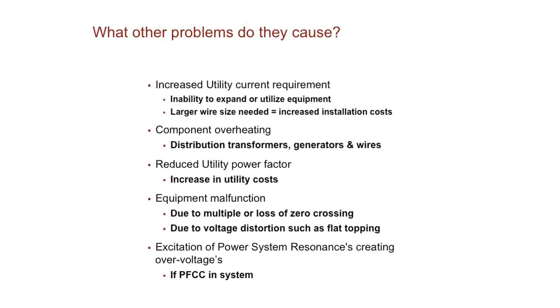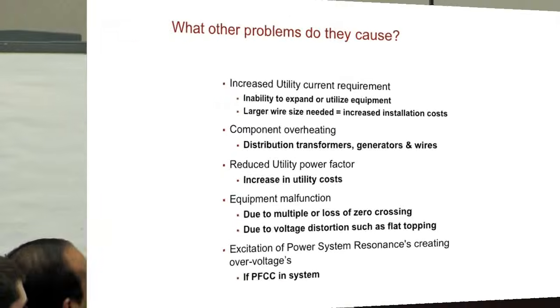One thing that it can do, and most people, this is their driving factor, is your power factor. Utility will fine you if you provide a bad power factor to your neighbor. Sometimes I heard a guy where he was getting fined 60 cents per kilowatt because he had a bad power factor. That's what the utility was charging him, pretty much for like a 500 horsepower drive that he had on there. So you can imagine what his bill was. So he was looking at a way to fix his harmonics in his system.